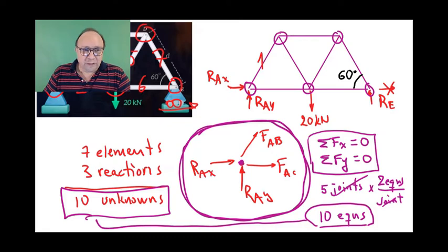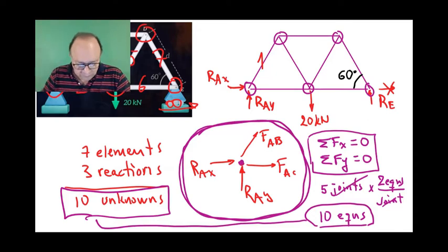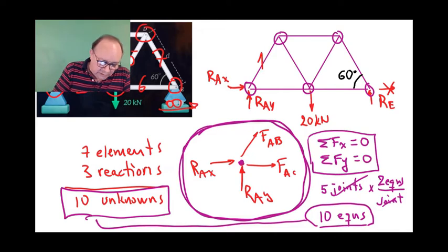So let's do this problem using the method of the joints. He did it really quickly, but I want to do it a little bit slower so nobody falls behind. Some of you probably have seen this before. It's a very easy method. You just have to be well organized and work slowly. Make sure that you don't make a mistake. If you make a mistake in one joint, then that mistake propagates through all the other joints, and all your bars will be incorrect. So let's get started with this.